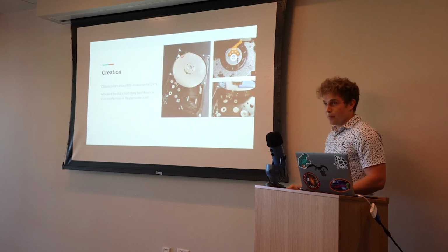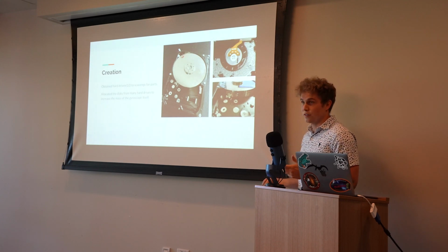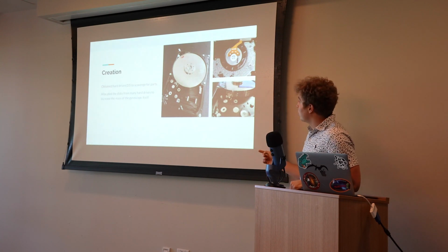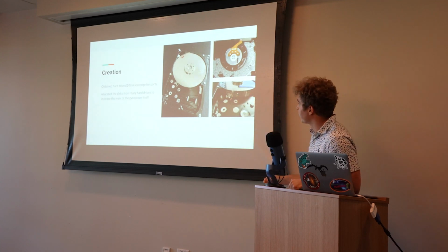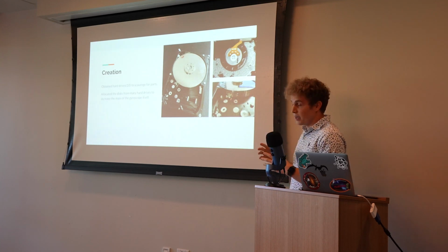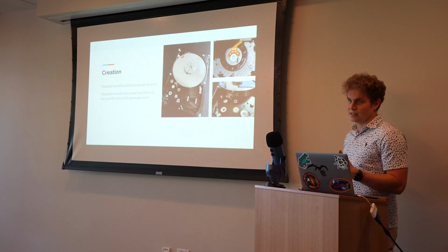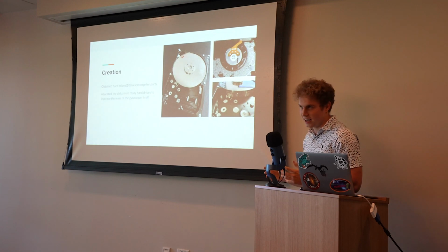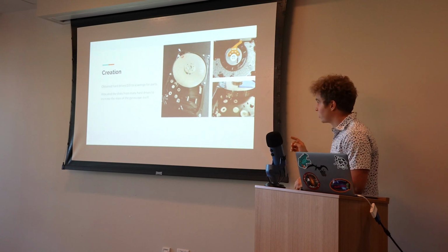The first thing I did was look at how other people had created their own gyroscopes. I found that most started with a hard disk drive, so I decided to do the same. I obtained 10 hard drives and scavenged these for parts, which were a suitable motor and platters, being these metal discs you see here. I put as many platters as I could fit onto my suitable motor to maximize the mass and therefore the gyroscopic effects. Although this seemed like a great idea at the time, it wasn't. It came back to bite me later, and we will talk about that later.